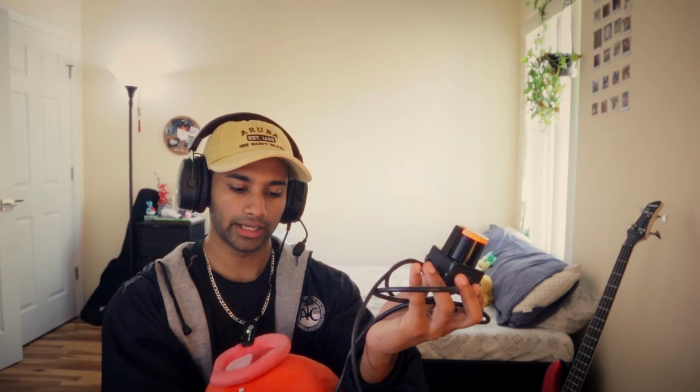Alrighty guys, do I have an update for you? Okay, where did we leave off? We talked about what a LiDAR is, and this is the LiDAR, and it has two things. It's got this Ethernet cable, and you have these wires. These wires have different purposes, but essentially, we only care about the blue. Is it the light blue? No, we care about the deep blue and the brown, because that's our 12 volt and our ground. So that's what's actually going to be getting the power to the LiDAR.